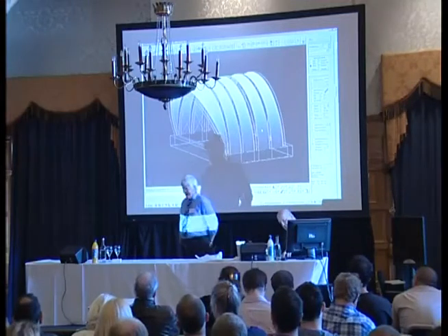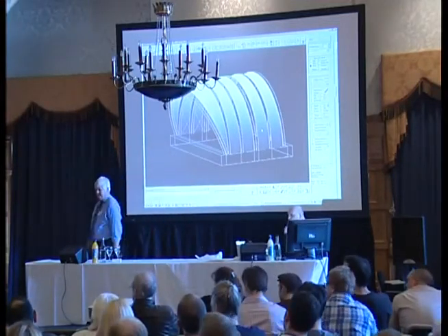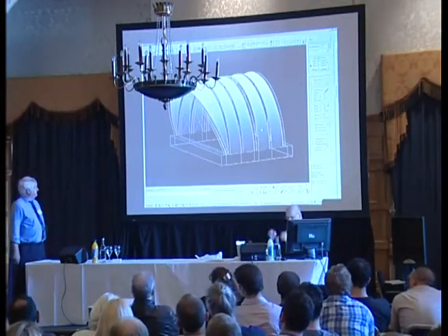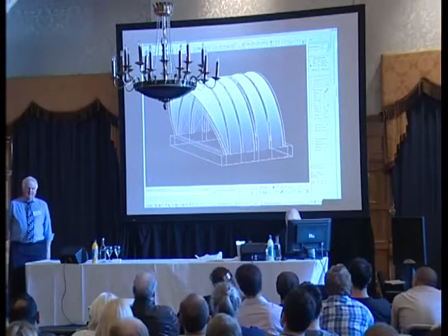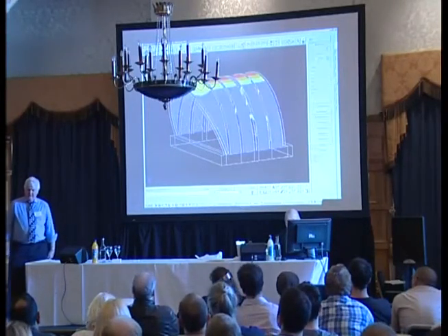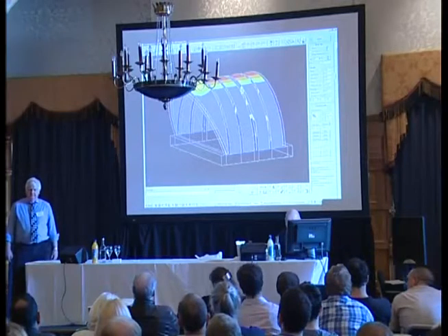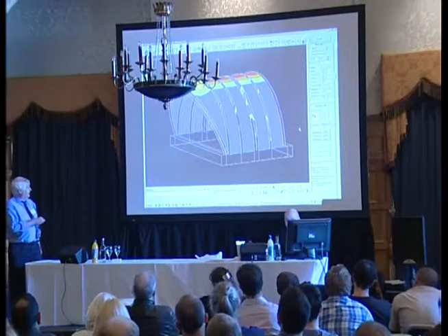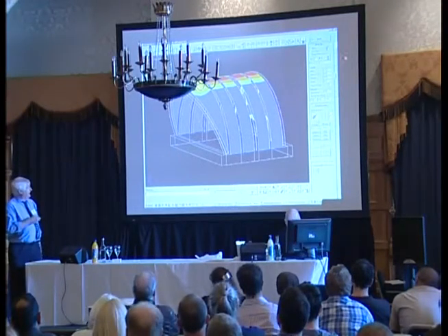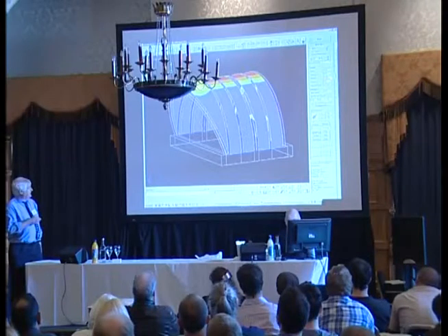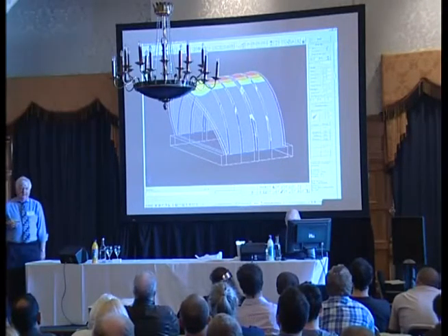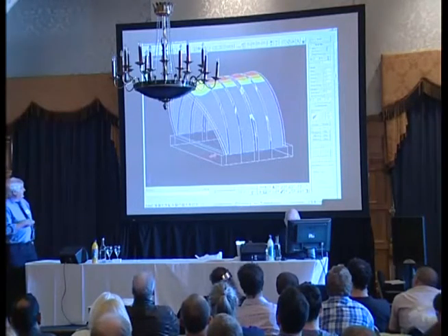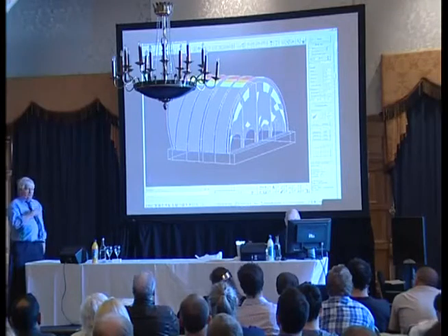Okay. Can I just ask about the load cases? You're setting those, I presume, for instance, like I see in the corner, it says wind 0.5 direction 1. So you set up whatever load cases you want for finding the worst case scenario in whatever direction. It's not tricky, you've got an arrow. That's the way the wind's going. And you set the load, outside load, inside load. For engineers, you've got your internal pressure, your external pressure, 0.5 to 0.8. And then you can apply uniform loads.